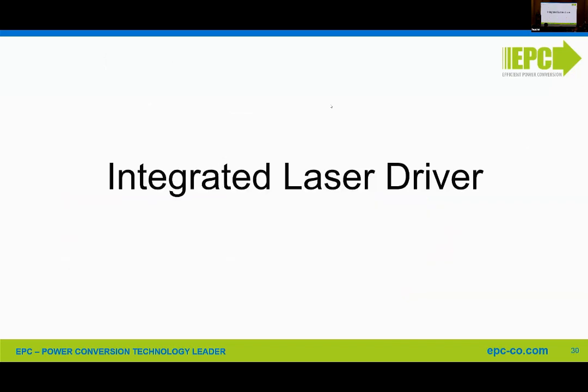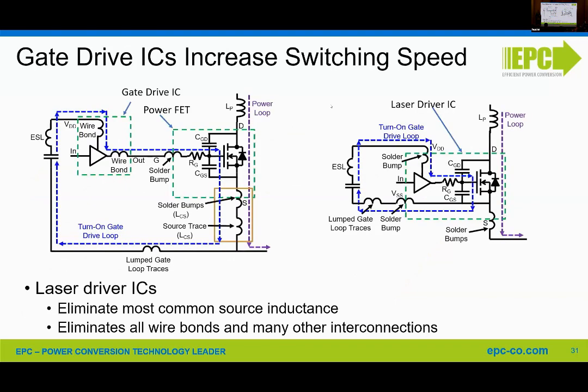So a little bit about integrated laser drivers now. The fundamental is that they reduce the inductance, particularly the common source inductance and the gate loop inductance of your laser driver. It eliminates most of the common source inductance, all of the wire bonds and many of the other interconnects. The only external path is through the power capacitor.